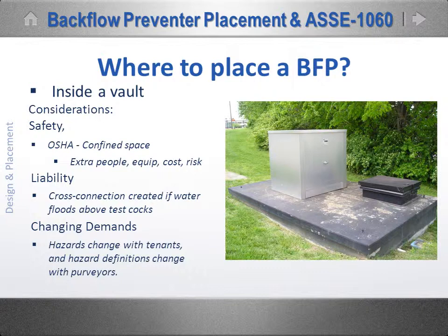Around the corner from our office in Nashville, I snapped this picture. It sits in front of a warehouse owned by an automotive dealer. When they bought the property and erected the building, they put a double-check backflow preventer down in that vault with the meter. A few years later, the city changed an ordinance that redefined their particular use as high hazard.